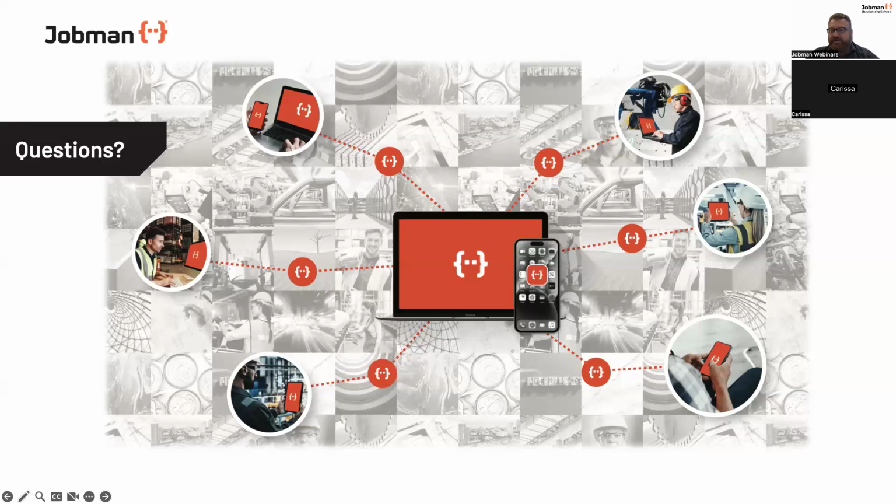But no, absolutely. The best idea there is to utilize components. So go in, make the product type, base cabinets, go into the components, create a side, give it those measurements, link it to a style item for carcass, and then link it to the product types, base cabinets, upper cabinets, tall cabinets, hit save, bang. That will then go and fill one side or two sides in this particular instance to all of those cabinets, ready to go in a click of a button. So absolutely, no, you're right.